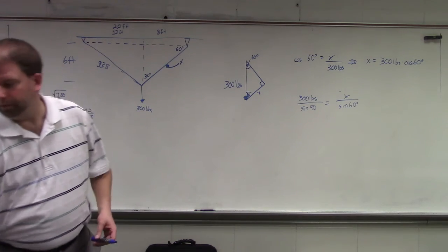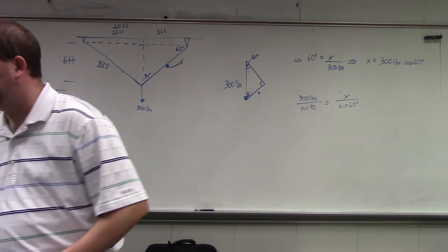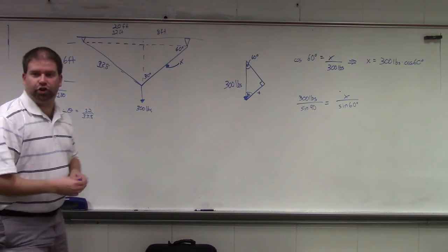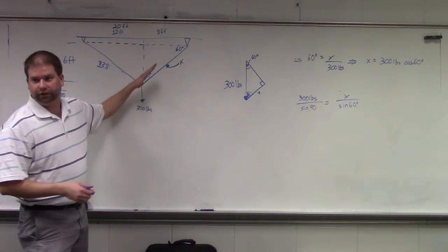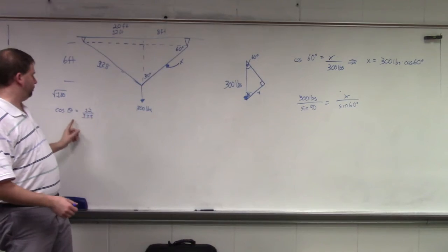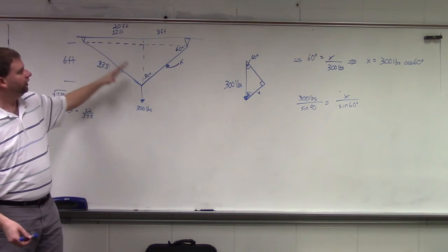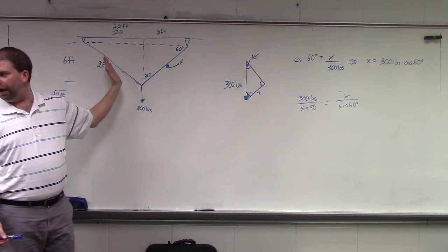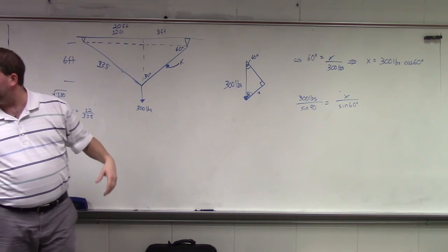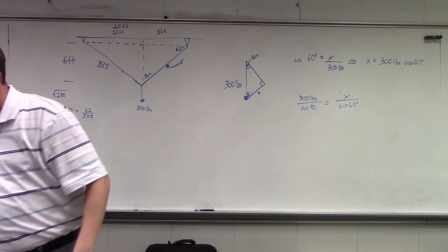Are we assuming it's 36? Yeah. What John asked is, are we assuming that it's a 30, 60, 90 triangle? If we don't assume that it's a 30, 60, 90 triangle, I was just going to calculate this for you, what this angle is. If you draw this the way that it actually is, you're not at equilibrium. Right. And you're going to yank one of those anchors out, or you're going to pull out of the reaction point.